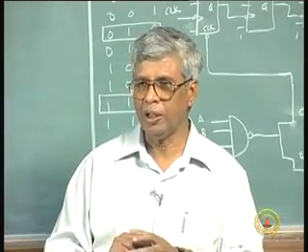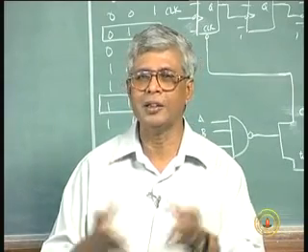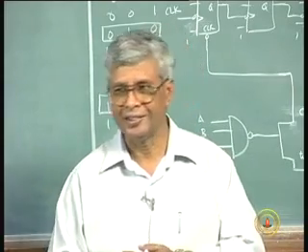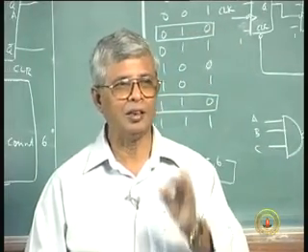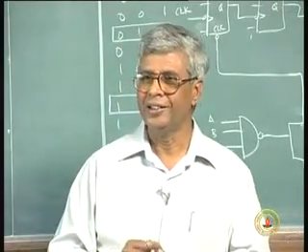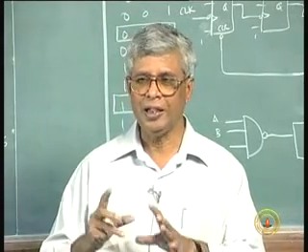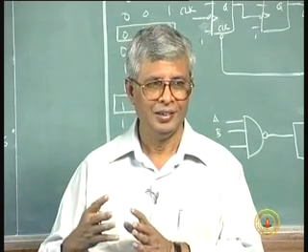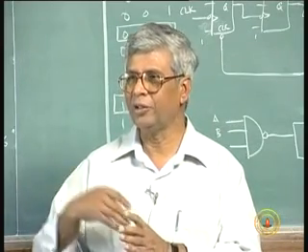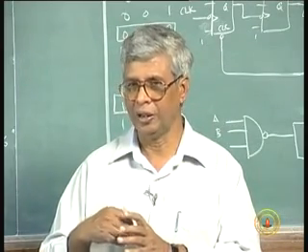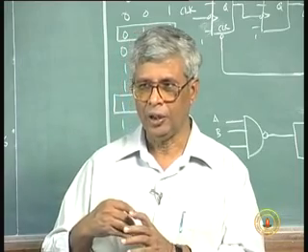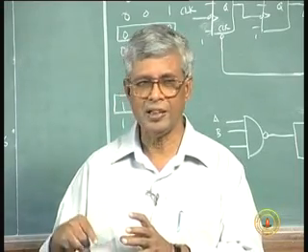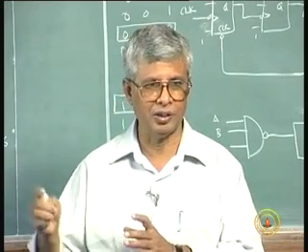So let us say, make it 3.6 megahertz. I am giving you a 3.6 megahertz clock. Design a series of counters so that I can get my frequency divided at the right time, with the right numbers, to have a count of seconds, a count of minutes, a count of hours. Okay?